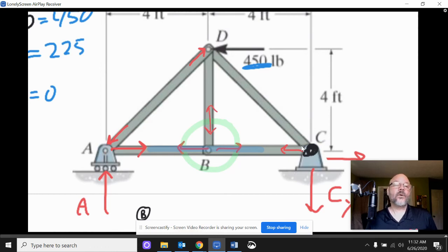beam. Okay. So you're pretty much only going to get, well, I don't want to say this is only going to happen when you have three beams that come together because there's other things that could come into play. But if you've got three beams like this and you can eliminate one of them by seeing that the other two form a straight line, great. You've saved yourself quite a bit of time. See, we didn't really need to do the whole joint at B at all. I only did it to show you that there's such a thing as a zero force member and how cool it is. And if you get to see it, give yourself a little fist pump. Okay. Pump, bump. You can bump your own fist if you want to.